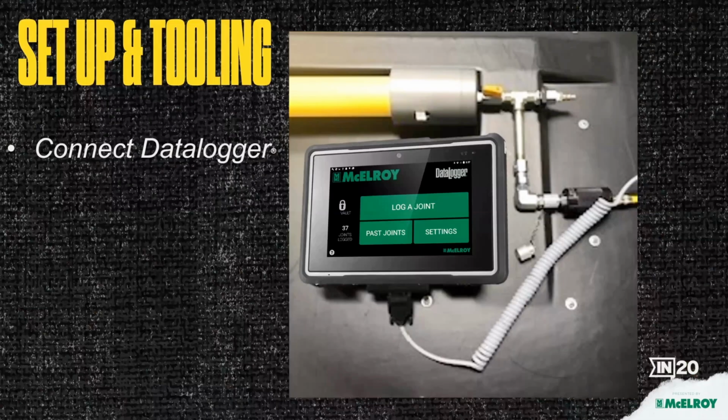With proper hardware in place, simply connect the DataLogger in the same manner that you would if you were connecting to a piece of hydraulic fusion equipment. Again, no changes need to be made to the DataLogger, the cable, or the transducer on the 6 or 7 in order to use the pressure test software. Just the additional quick connect and plumbing.